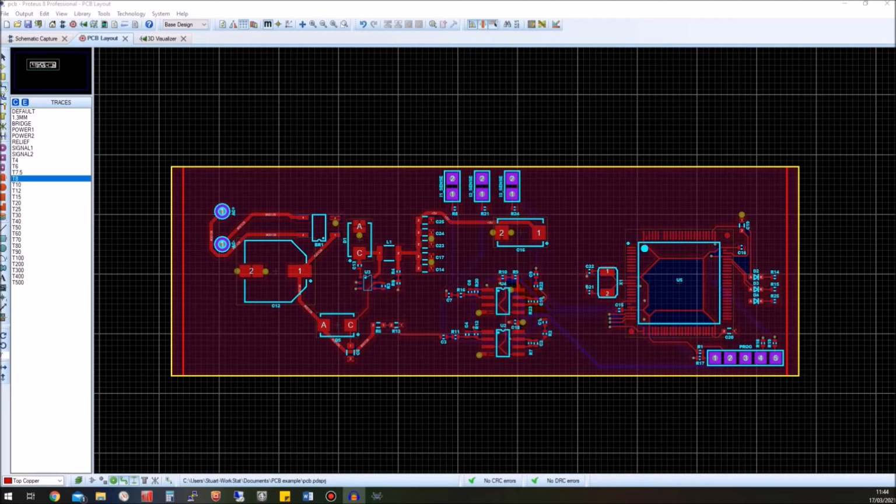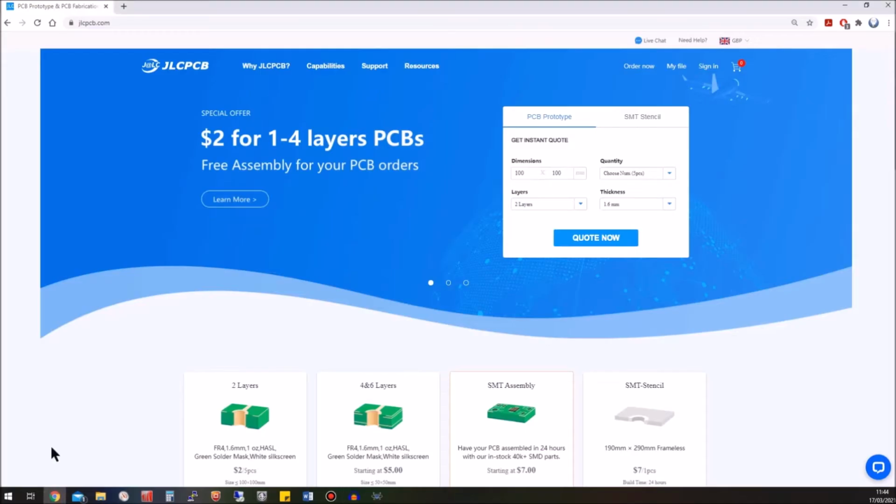The university offers a PCB manufacturing service, where you can submit Gerber files alone for simple PCB fabrication, or Gerber files accompanied by a bill of materials and a component placement file for surface mount assembly. PCBs are manufactured through JLCPCB, and they have certain requirements for the files that are submitted to them for manufacture, which is what I will outline in this demonstration.